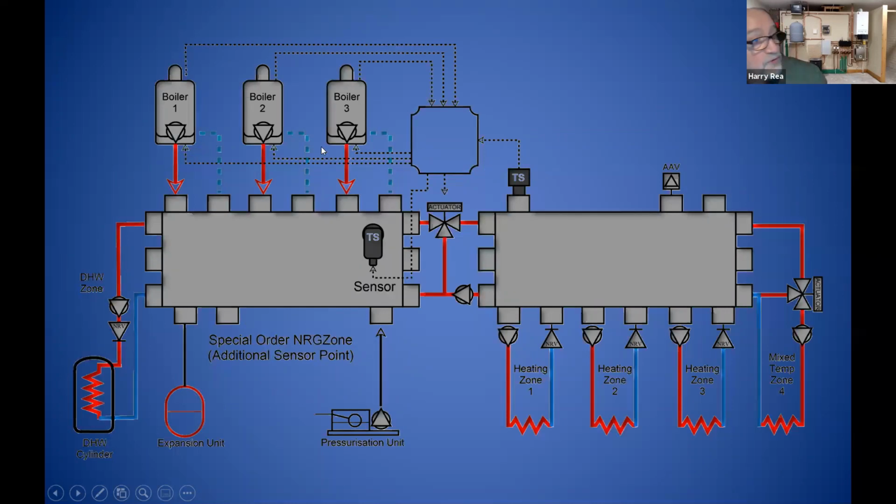Again, same scenario, you could have wall-hung boilers, mixing valve separating the temperatures from the high temperature to the low temperature, and again, scenario with your hot water, pressure vessel and cold feed, or the filling system perfectly located on the neutral point. Your expansion is exactly right where it should be feeding the boiler, so everything is good.